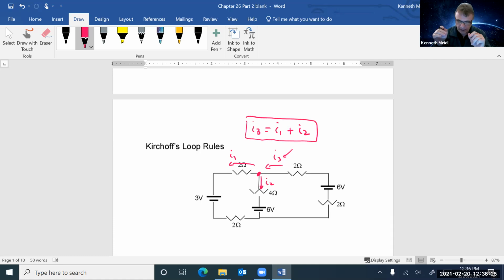That's one equation, and immediately you see that there are three unknowns. And so this is still not a very complicated situation. You can see all of a sudden I've got three unknown currents, because there really are three single lines in here, right? I've got the line from the junction going to the left, I've got the line from the junction going down through the center, and then I've got the line coming into the junction. And so all three of those will be carrying three different currents, and we've got to find all three of them. So what that really means is that we need two more equations to be able to get three equations and three unknowns and be able to work this through here.